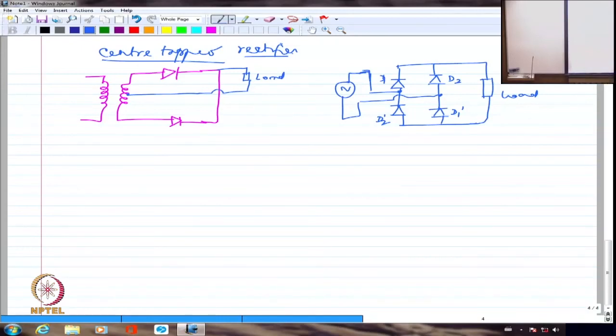Whereas in the other case, two diode drops, which will amount to maybe, especially if it's a silicon diode, 1.5 volts, 1.4 volts. I may get a very large drop out of a 5 volts power supply, which is definitely not a good thing. That's the reason why generally bridge rectifiers are more used with motor drives or large power applications, whereas center tap rectifiers are generally used with power supply applications. And power supply applications want to minimize the drop, so Schottky diodes also go hand in hand with this. Right? So much for the 3 types of diodes.